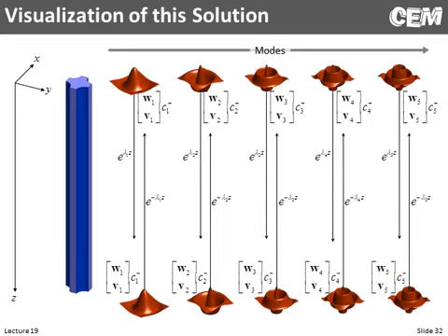So here's how I envision this happening with a semi-analytical method. We have a number of different modes, and we'll probably have several hundred of these for a fully three-dimensional problem. If we look at one, it's the first order mode probably. We have a column vector, which is its eigenvector. This first part describes the electric field components. The second describes the magnetic field components, and it has some mode coefficient multiplying it. And the plus superscript means it's forward propagating, going from top to down.